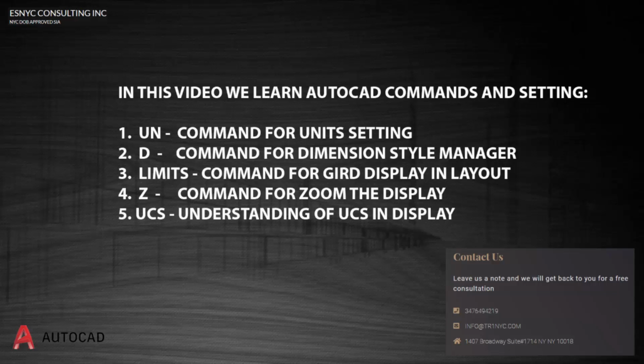In this video we learn AutoCAD commands and settings. 1. UN: command for unit setting. 2. D: command for dimension style manager. 3. LIMITS: command for grid display in layout. 4. Z: command for zoom the display. 5. UCS: understanding of UCS in display.